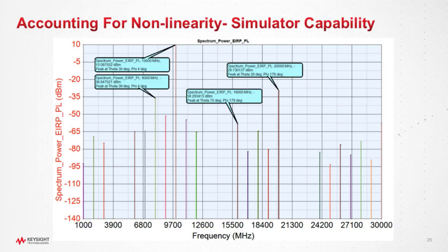So we are showing all the useful information in a 2D plot here, because what we are interested in is the maximum value of that spurious frequency that is getting radiated. If we reduce that maximum value, naturally the far field pattern will reduce, and we probably eliminate or reduce the radiation of the spurious frequency. Another important thing is that we can show all the frequencies very clearly, very visible to our eyes, in a 2D plot.